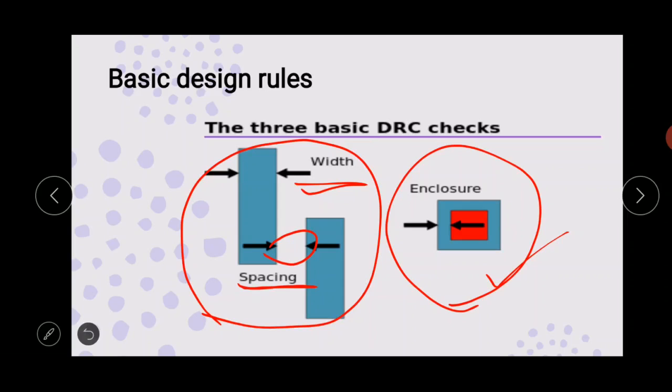The design rules do not represent strict boundaries which separate correct designs from incorrect ones. A layout which violates some of the specified design rules may still result in an operational circuit with reasonable performance, whereas another layout observing all specified design rules might result in a circuit which is not functional or has very low performance.